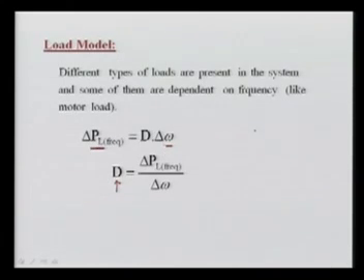It means the total load PL has one part that is independent of frequency, and another part that is dependent on frequency. Whenever you change the load, there will be a change in the frequency independent loads and the frequency dependent loads.